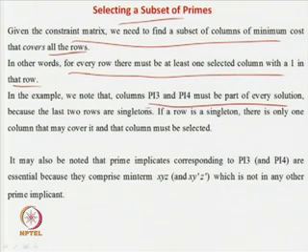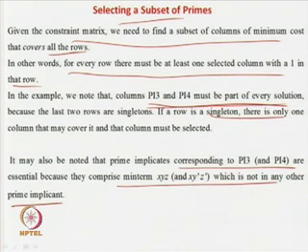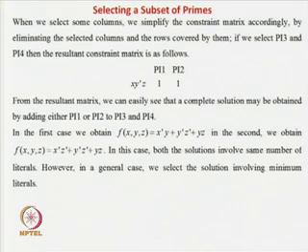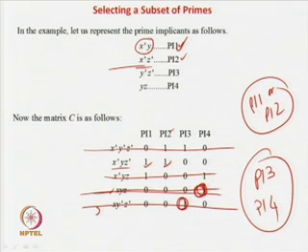This prime implicant is a part of every solution because these rows are singletons. It must be noted that these prime implicants contain terms which are not in many other implicants, so these are essential prime implicants. Now, what we have done is the reduced matrix. How does it become a reduced matrix? By virtue of this one being taken, this is gone, and finally this is the only thing that remained.